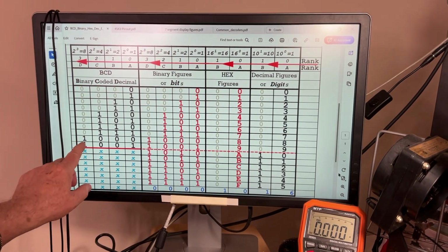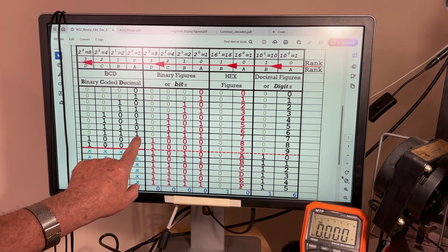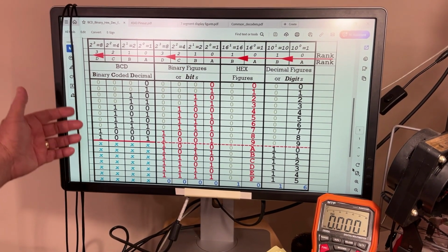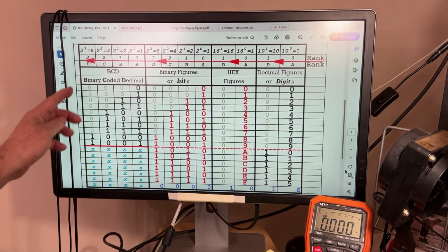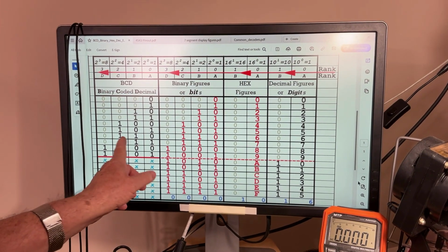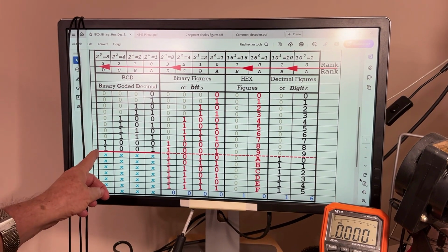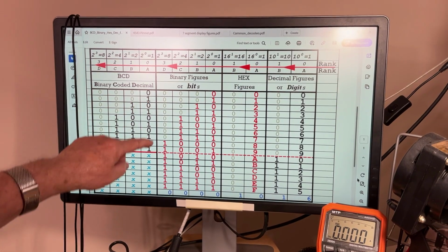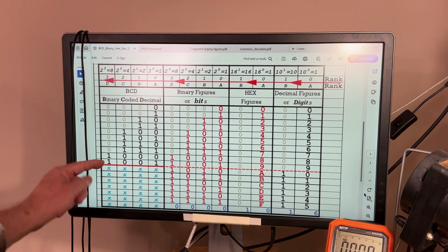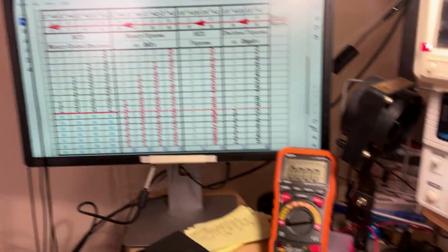But if you want to code the number 8, 3 digits are not enough, because on 3 digits, the biggest number you can code is 7, okay? So only for the 8 and 9, you still need 4 bits. For that reason, the engineers established a code made on 4 digits. So for the numbers which don't actually require 4, you can put zeros before, because zeros before any number won't change the number. So on 4 bits, they code all the numbers from 0 to 9, but they won't recognize any combination which is coding a number bigger than 9. So this is why here you can only see X's everywhere, because these are not recognized. It's exactly what you see here.